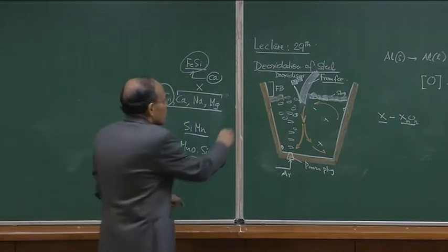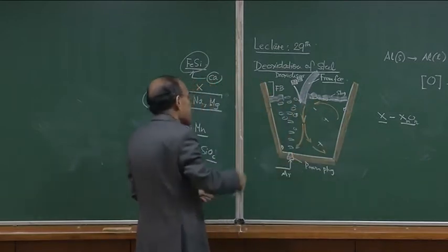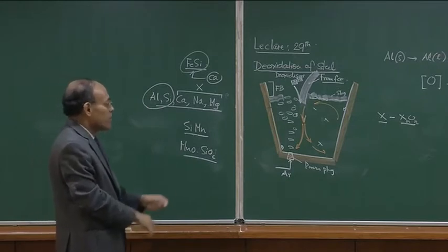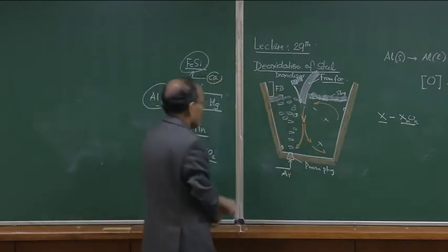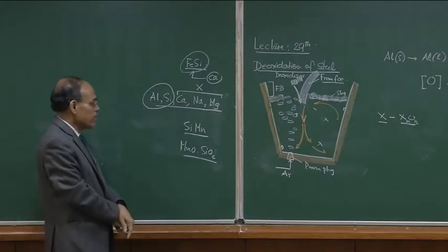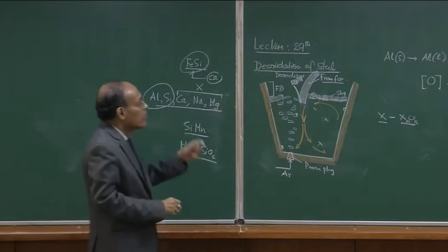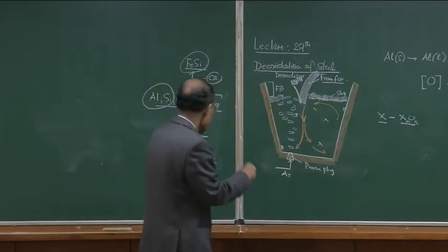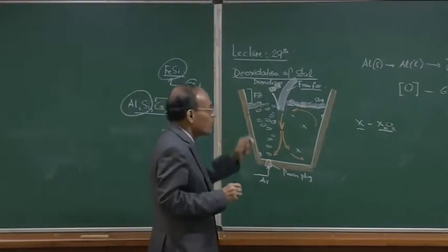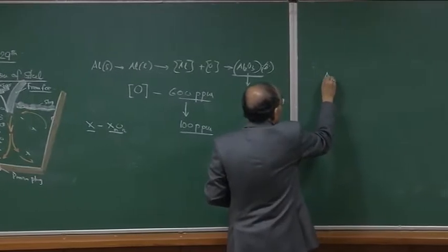So if you have a liquid slag, if you can engineer the slag properly, the slag should be able to absorb manganese silicate as well as Al2O3 particles, which will be continuously rising through the melt itself. Having given you this background, and the preliminary aspect of deoxidation addition during the tapping operation, let us look at the thermodynamics of the deoxidation reaction.